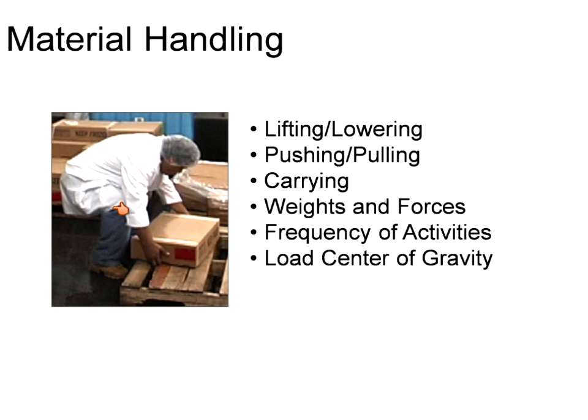Okay, and material handling. You see how the man is positioned. This is a very, very wrong position. You see, his knee is here, and he is not taking any rest here. He is hanging his backside, and he is bent. Everything is in a very wrong position. Definitely, it will give a problem on the back. Instead, he can kneel down. He can put one of his knees on the floor and take it. After that, he can move one step and put it in this place. This kind of wrong position is also another reason to get back pains.